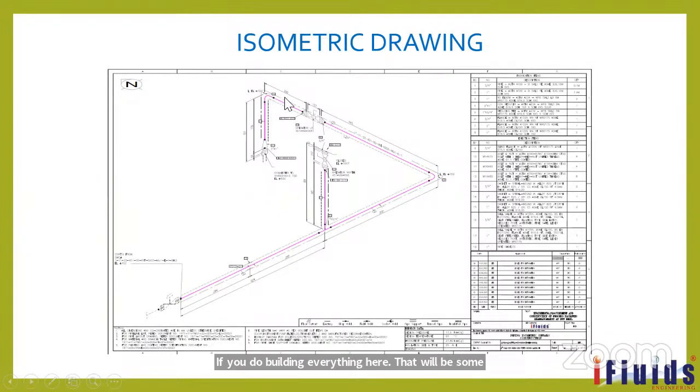That and all we have to do at the site, because to save time we cannot do all the joints in shop joint. Same, to avoid the mistake, we cannot do all the joints at the site. It will cost us the time. So that one we will mention at the bottom of this isometric, which one is shop weld. You see here, this is the shop weld. This mark will be shown as the field weld. So like that we will mention it normally.